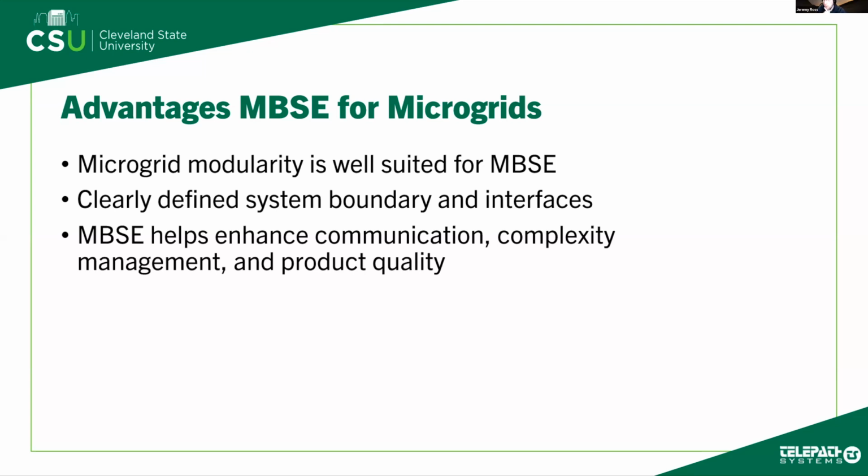And then there's an aspect with microgrids as being a little bit of a more novel system. We need to be able to communicate and manage our complexity across interfacing stakeholders. We're going to be implementing our design in a building environment. Do we have a representation where we can say, hey, here are the interfaces that our system is going to have with you. Here are our assumptions, maybe from our standard design, that we're going to convey 240 volt AC at X amount of current, or we're going to use this common connector type, this part number, or at least this connector element. We're going to relay digital information using this protocol.